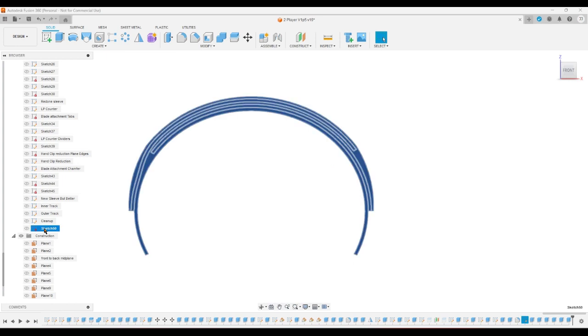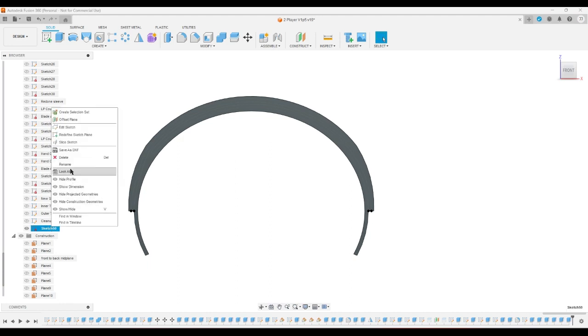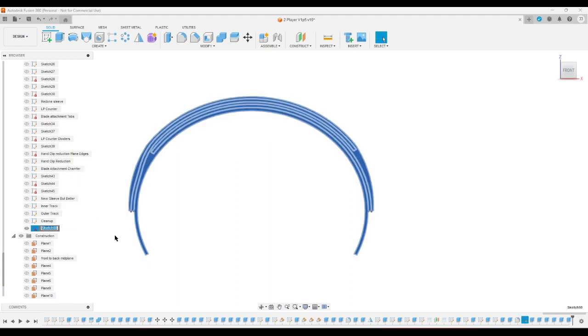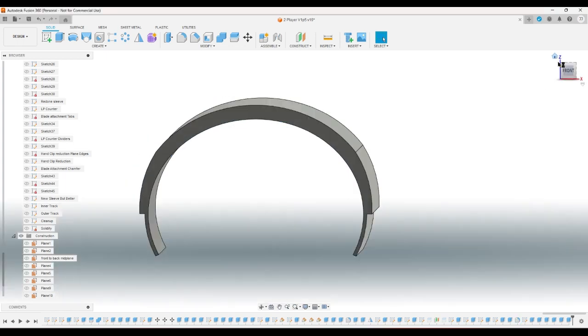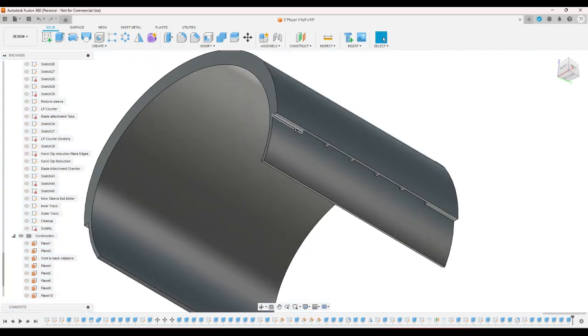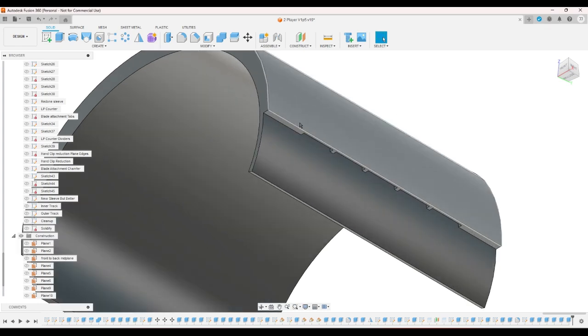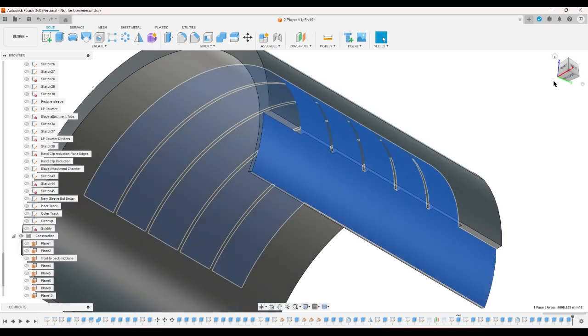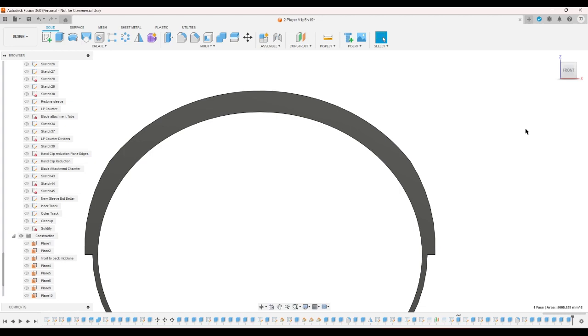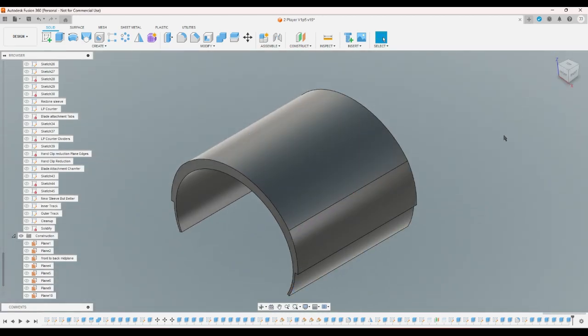Okay, and then this sketch was... What was the sketch? Solidify. Yeah. So the reason I need to close it off on the ends there is so that it's one piece, right? If I didn't close it off like that, then it was shaped like an accordion and could just come apart by itself.